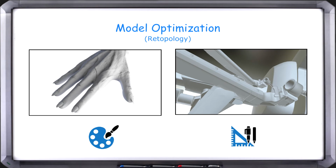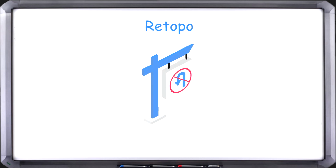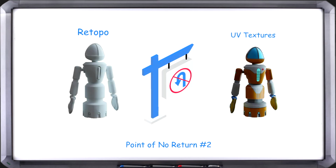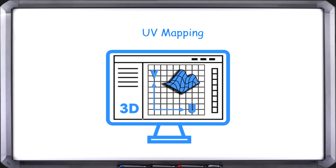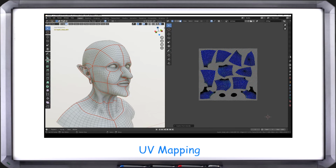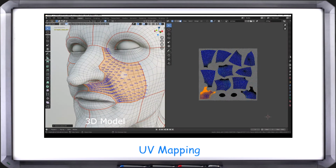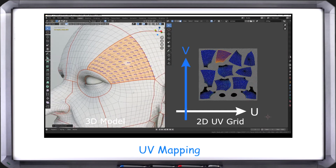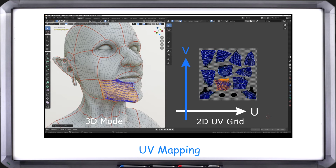This is done with textures, usually image maps. This is an absolute point of no return milestone. Coming back to this step after the texture process is complete will break the texture link to the mesh. To prep for the 2D texture process, the mesh must be embedded with data to convert the surface area of a 3-dimensional object into 2-dimensional texture data represented on a U and V direction grid. This process is called UV mapping.